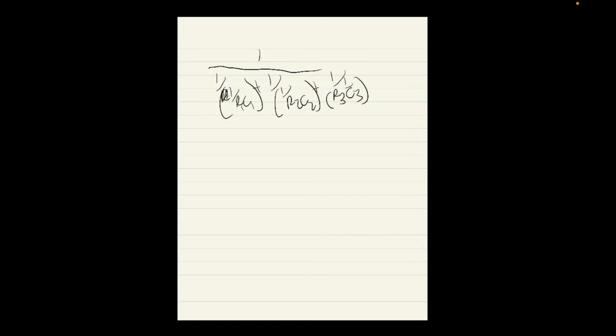These 1 on RCs, I can just call them the poles, the same definition I used before. 1 on pole 1, plus 1 on pole 2, plus 1 on pole 3. Does this equation look familiar to any of you? Have you seen this somewhere when you're simplifying resistor networks, potentially? They're all in parallel. That's what I'm trying to say. P1 is in parallel with P2, is in parallel with P3.